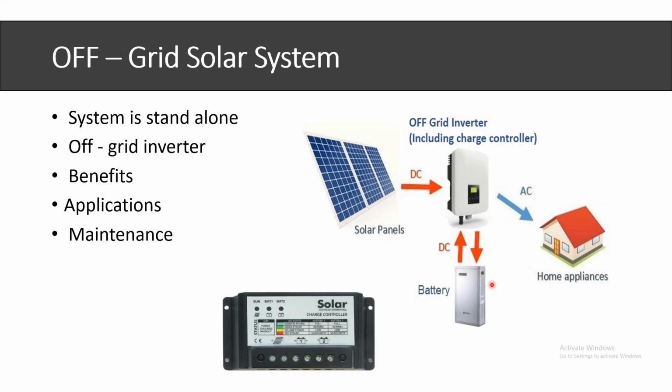Okay, you need to have periodic inspection as well to see the condition of the battery, what is the discharge rate of the battery, or if you are using lead acid battery, so you need to check the fluid levels in the battery. This thing you can see on your screen, there is basically a charge controller.